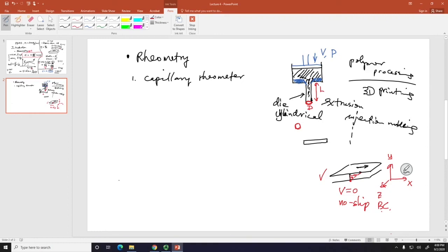So under the no slip condition, when you think about extrusion through a die, necessarily whatever material is coming through this die, you take a free ride, you're coming out as this piece of, we call it extrudate. As this piece of material comes out, the material near the wall will attain 0 speed because the wall is the surface that doesn't have any velocity.